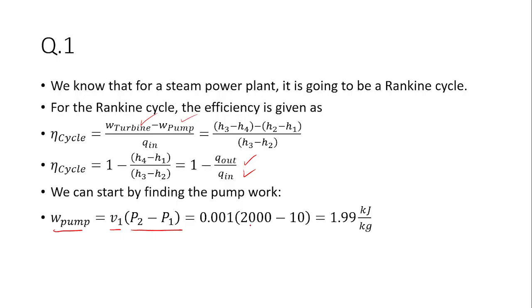We are working with water, so this is the example I was saying, that the density of water is 1000 kilogram per meter cube. It's going to be fairly constant over a range of pressures, right? So if I'm going to compress it, then my specific volume is 1 over my density. So that's 1 over my 1000. That's where I got the 0.001 from. So that's here.